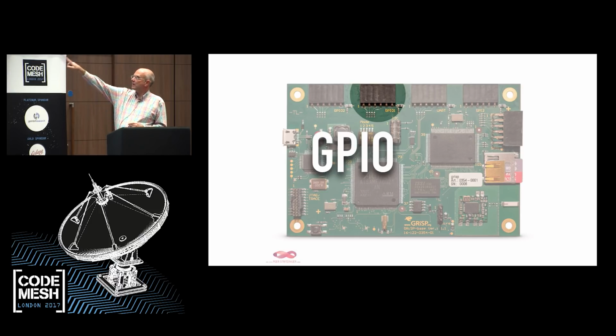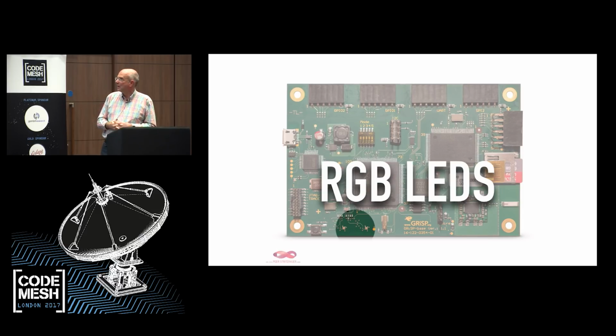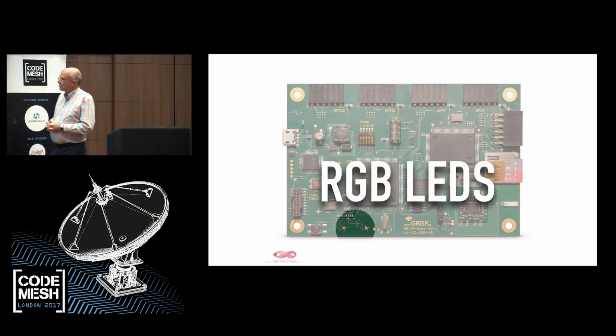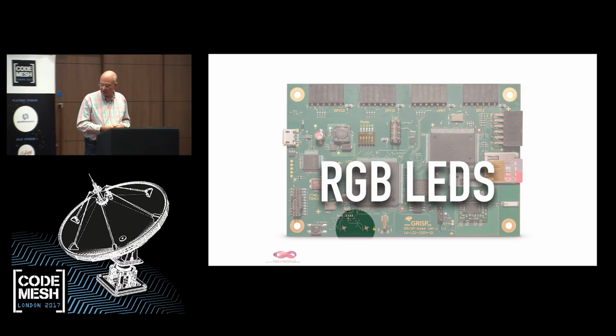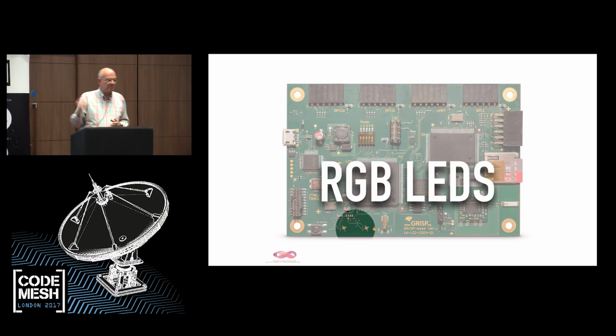And by the way, all the connectors can be GPIOs. So if you don't need the other ones and need lots of GPIOs, you can configure them. And then the writing on the connector is not correct anymore, because then it's not an SPI, but a GPIO. So every pin on the CPU basically can be GPIO. Also wired to pins on the CPU, we have RGB LEDs, 2 LEDs, I mean, to indicate. So you see one green here, that basically means my application has booted. Or you can do blinking lights and whatever things.